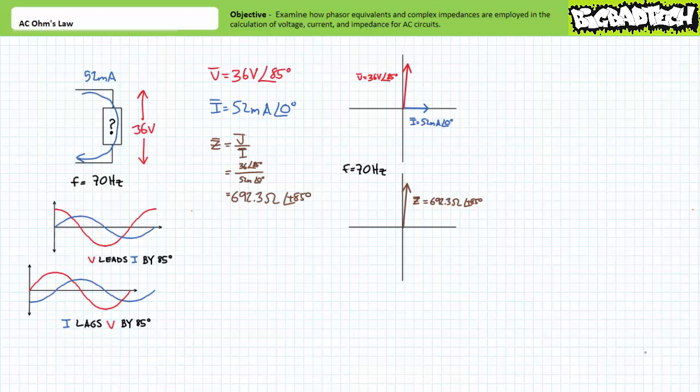As we previously discussed, the impedance magnitude of reactive elements is frequency dependent, and as such, we cannot expect to find an inductor with an impedance of 692.3 ohms at an angle of 85 degrees at the inductor store downtown. If this is a purely inductive element, ordinarily we'd be able to directly algebraically rearrange the inductive impedance formula to solve for the inductive value that satisfies this condition.